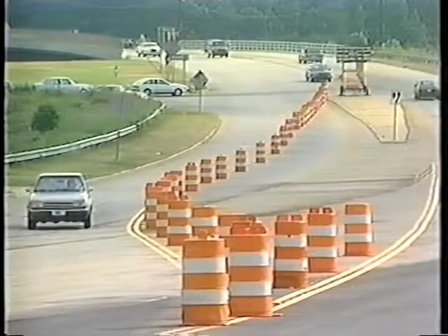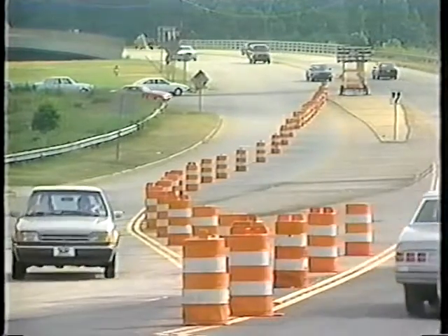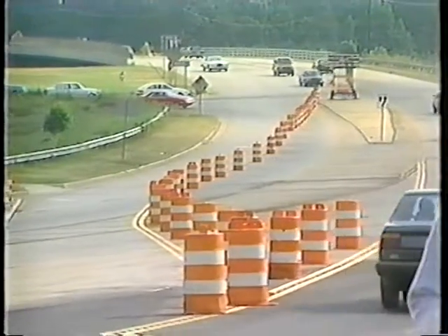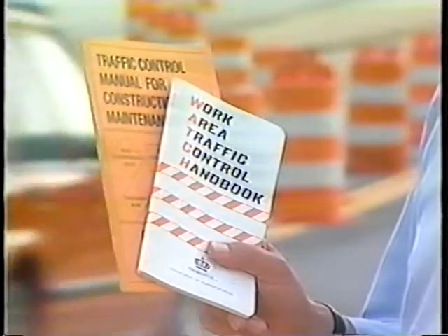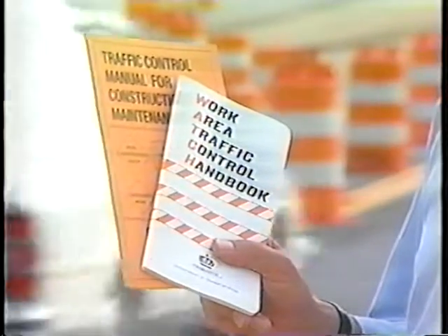We've reviewed the need for traffic control at work sites, examined the traffic control zones, and looked at the standard traffic control devices. Now we want to take a look at some typical applications of work zone traffic control. The various state and local supplements to the Manual on Uniform Traffic Control Devices provide detailed layouts in addition to those shown in the MUTCD.